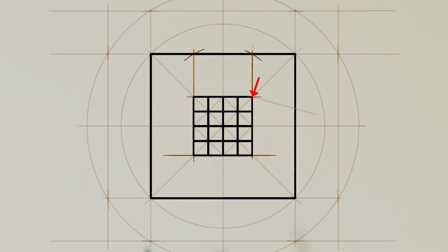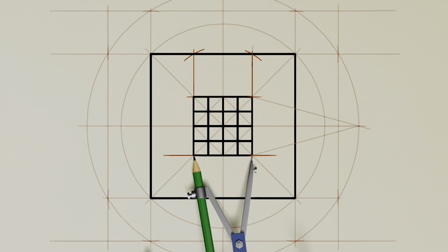Now let's focus on the smaller square, which we already divided into 4 parts with guidelines. We'll divide it once more to create 16 smaller squares. Then we'll trace the remaining diagonals to complete the reference points and finally reinforce the lines in black. From the corners of this subdivided square, draw lines that extend outward to meet the horizontal line and the outermost circumference. To determine the back edge of this square, use an auxiliary square of the same size, placing it along the lower side.